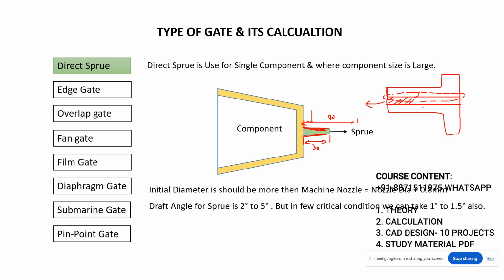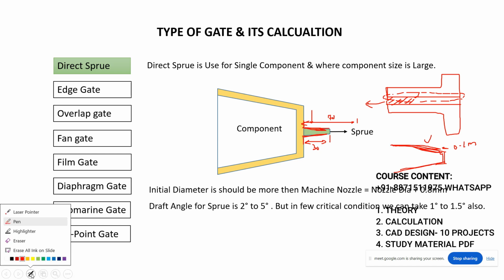But if you take the draft, it will move around 0.1 mm and it will detach because of the draft. That's why draft is very, very important.